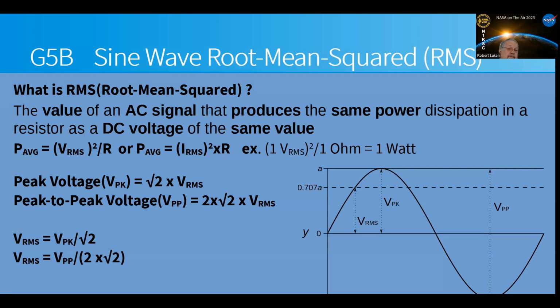The numbers are different. If it was a square wave, it's simple. Flip the other half up, and it's whatever that is. Triangles and sawtooths, it's much more complicated. And the perfect square wave doesn't exist either. Sure. Don't have enough harmonics. So if we have the peak to peak voltage, we divide it by 2, right? To get the peak voltage, and then we do the RMS calculation.